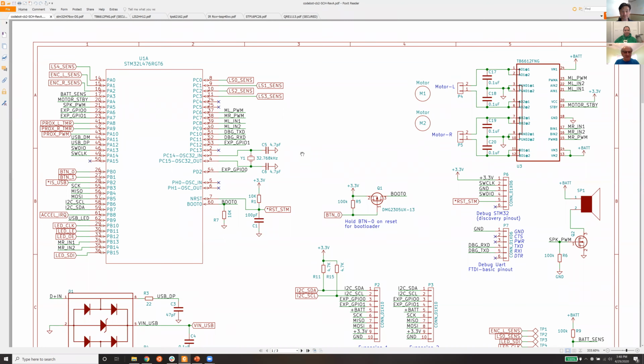So I seem to have heard that you have an IR sensor, but you also have proximity. Do you have both, meaning for distance? Yes. So these little front-facing sensors here, they are infrared. Those are those two Vishay infrared sensors. And those are what we're using to sense proximity. Oh, for line followers, say. No. So the line followers are underneath. So there's 5 line followers here that have a photoreflective switch.